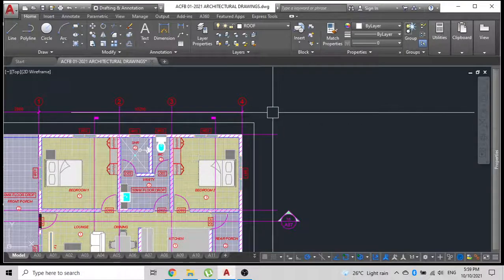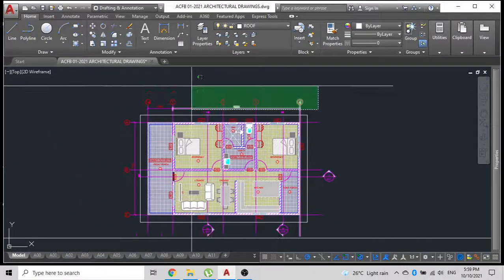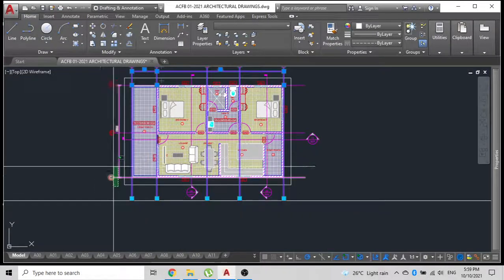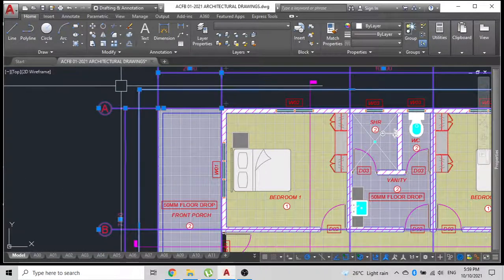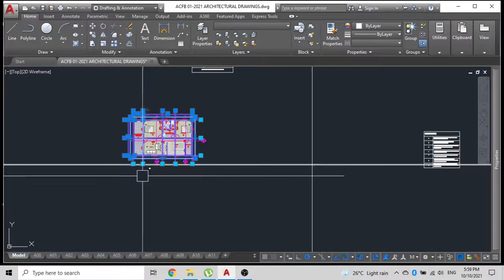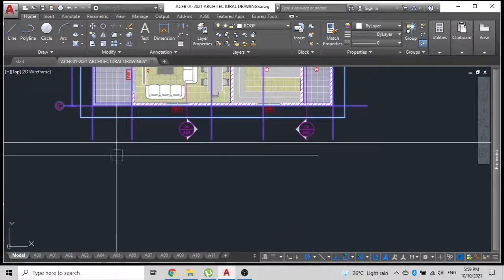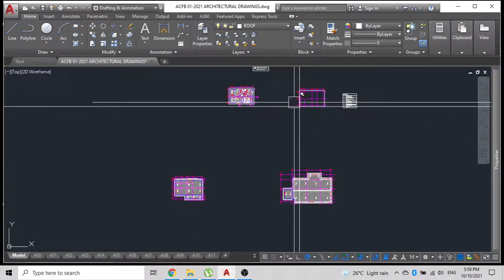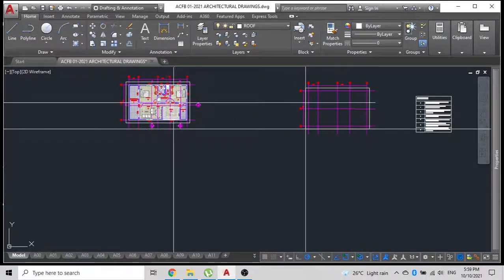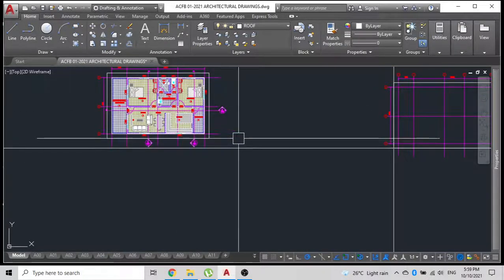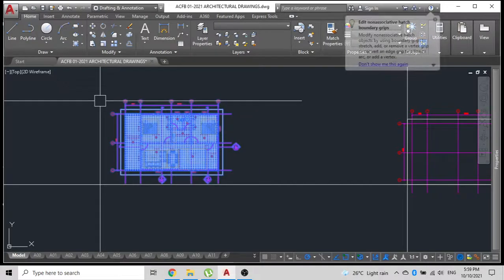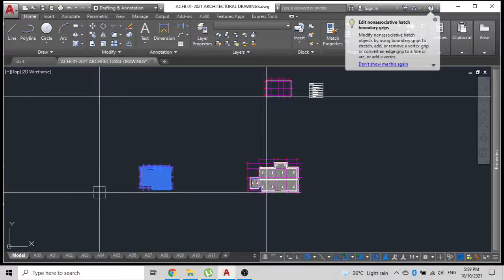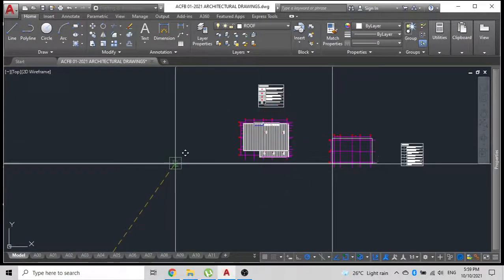So, to create a roof plane outline, you don't have to create much, you just have to copy your grids like so. Then you select the roof outline only. Don't worry about the gutters. Copy from your original base point and then place it over where you have set up your work like so. Now this is no longer important to us, so what we can do is simply delete this. And we'll bring up our roof that we had drawn earlier and use that as our reference.